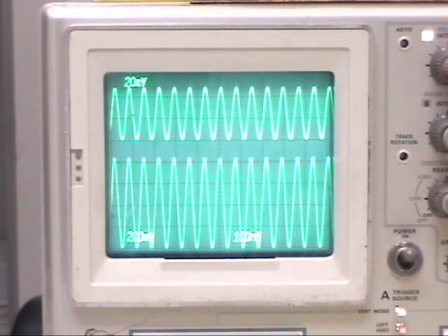And 20 dB is a factor of 10, either 10 times as much or 1/10. We put 20 millivolts in and we got 297 out. That's more than a factor of 10 by a little bit, so we have at least 20 dB of gain out of the amplifier. So if we calculate that all out,